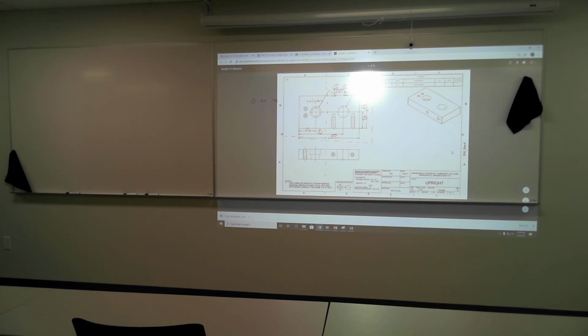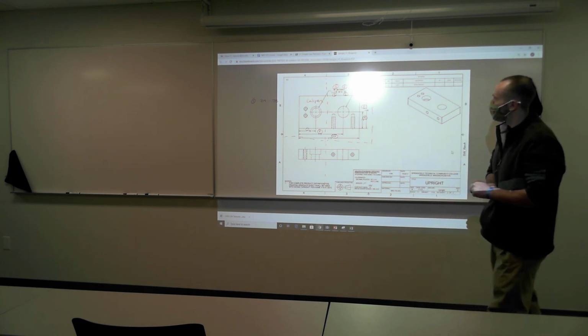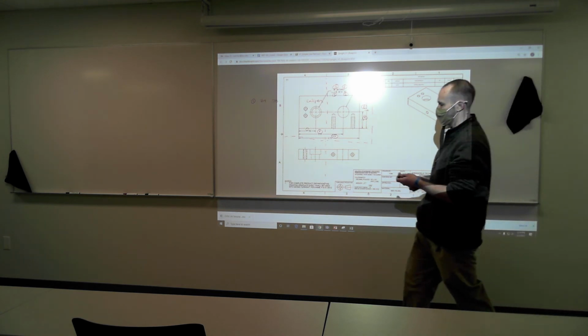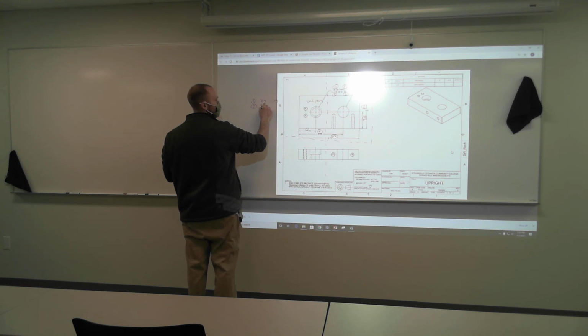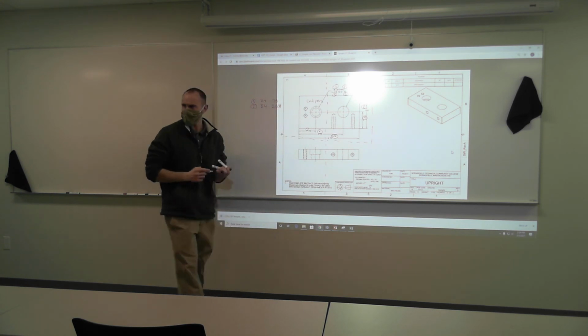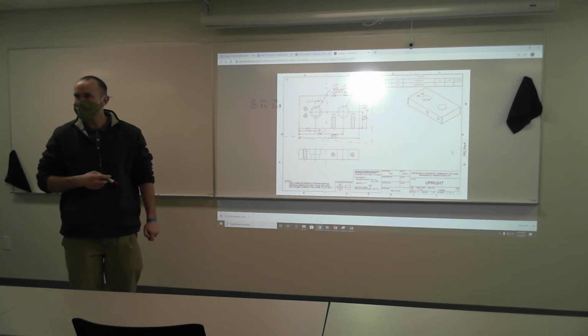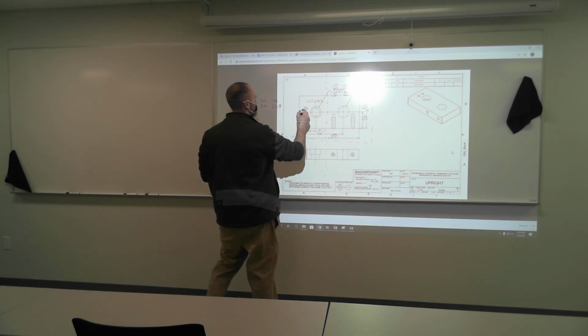All right, so how about balloon number 2? Let's fill this out quickly. Balloon number 2, yep, it's B4 as well. 2.03. 2 inches, 30 thou. Yep. It is a 2-place decimal, so we got plus or minus 10. What would we use to check that? Calipers as well.